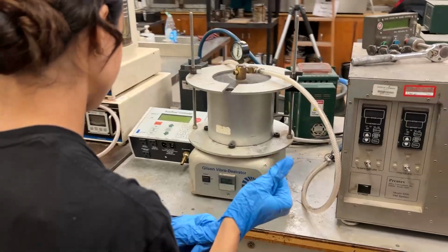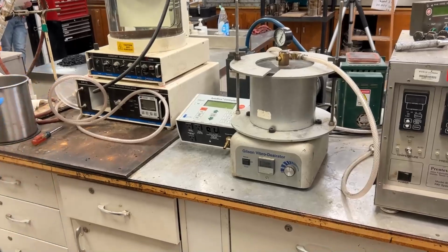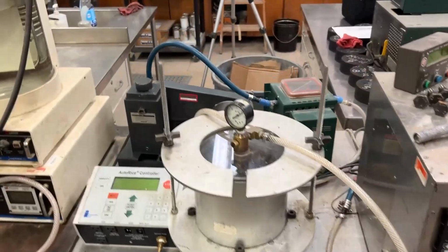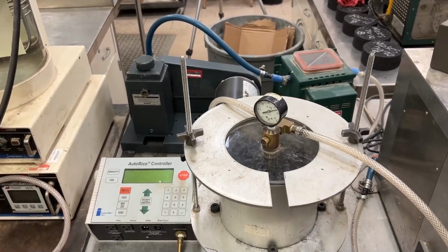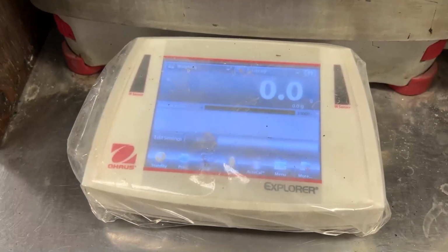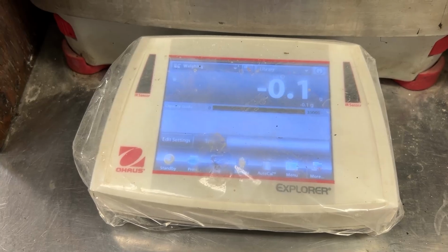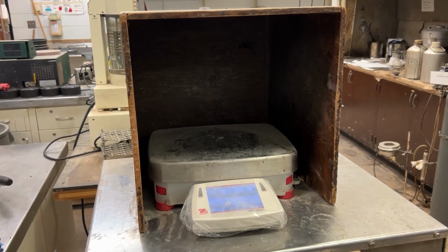A vibrating table or shaker to perform consistent, automatic agitation of the vacuum pyknometer, and a bleeder valve attached to the vacuum train to facilitate adjustments of the vacuum being applied to the pyknometer. A ballast conforming to the requirements of M231 Class G3. The ballast shall be standardized at least every 12 months.